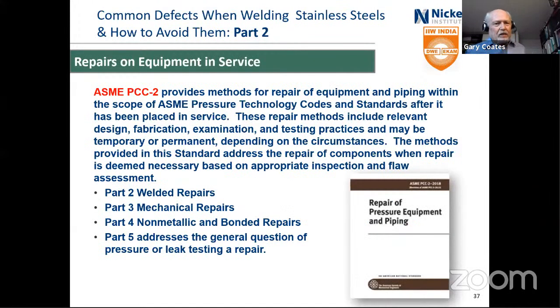So, and I just always refer to ASME has a book called PCC-2. It really talks about repair of equipment and piping within the scope of ASME codes. After it's been in service, it covers non-metallic, it covers mechanical repairs as well as welded repairs, and various other things. So it is really the standard to go by for repairing. Now, it's not perfect either, and doesn't cover a lot of the special cases.